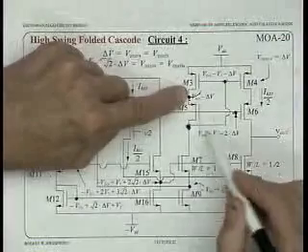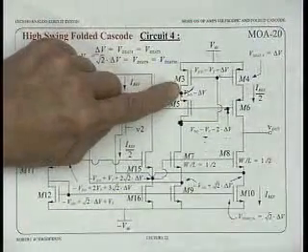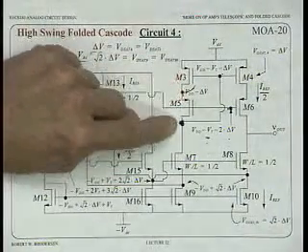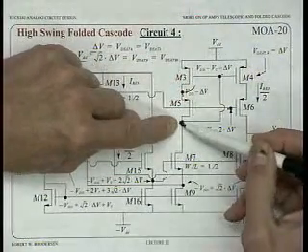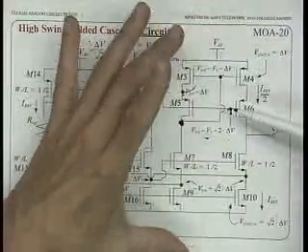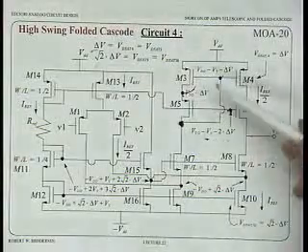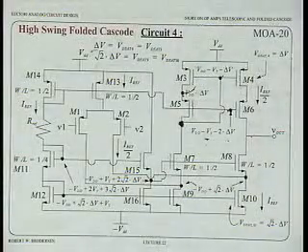But just by connecting this up, I get a VT plus a delta V. So I get plenty of voltage to put this guy in saturation. So it's more than enough. But this doesn't have to be right at the hairy edge. It might be a problem if we really start squeezing down the supply voltage because we've got more than enough voltage across here, but this isn't where the output's connected, so this is all right. Whew.